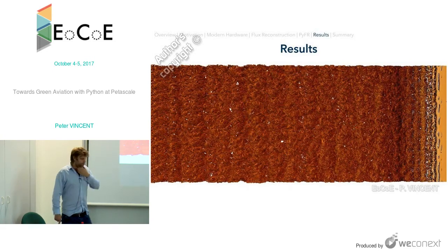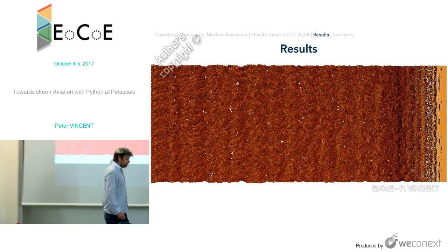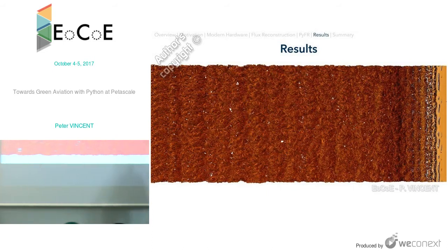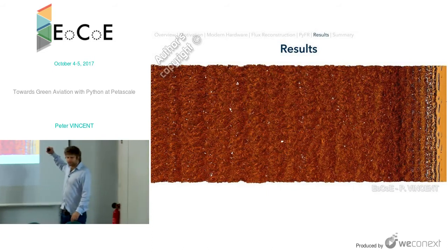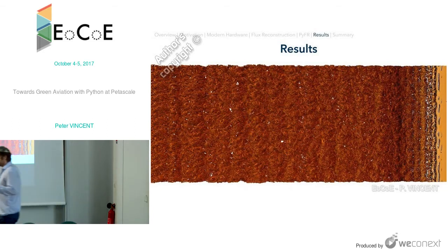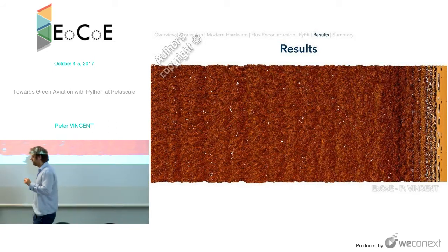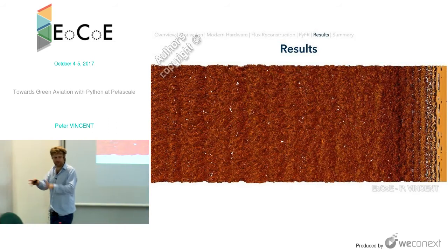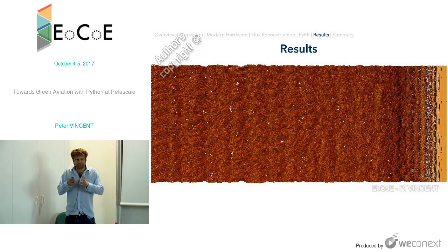We're further developing this at the moment so that it works live. We've done it on a smaller problem, but not on a problem of this scale. So you can fire up ParaView and look at a simulation as it's running and zoom in on pieces. This in situ visualization, and generally in situ analysis, in situ being in memory as it's running, these paradigms are super important if we're going to perform useful simulations at this scale.